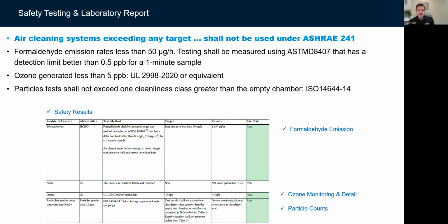One of the things that it does mention as part of the building readiness plan, or that IRMM, is the equipment needs to be maintained. Filters need to be replaced. If it's a UVC lamp, it needs to be maintained in some interval. So it says in the standard, you need to address what preventative maintenance measures need to be used to make sure the equipment is in good working order, but does not talk about its effectiveness over its lifetime.